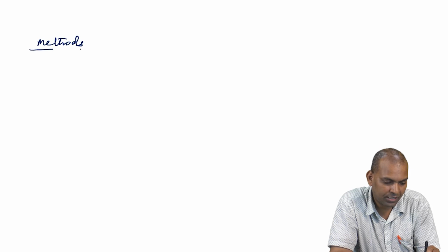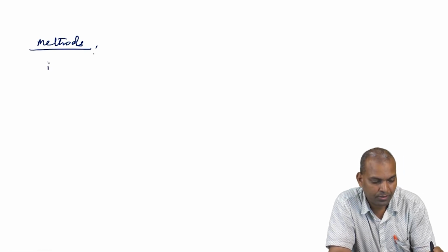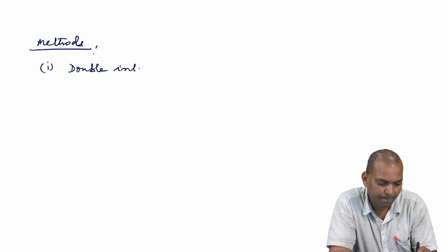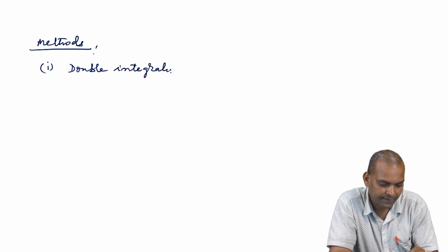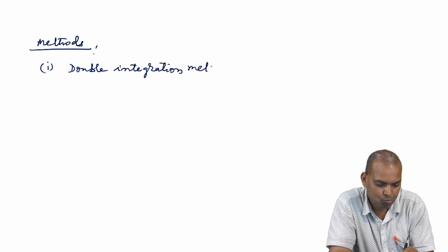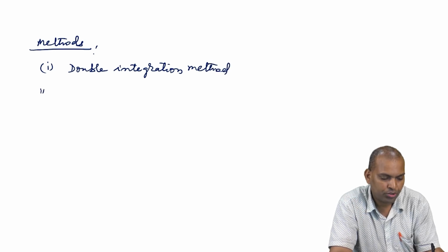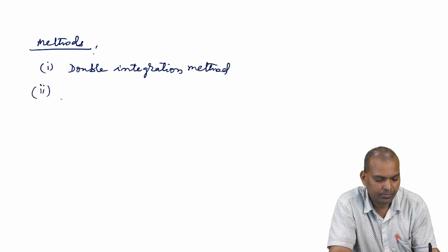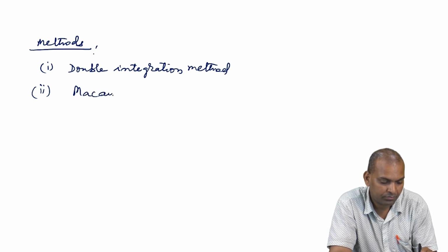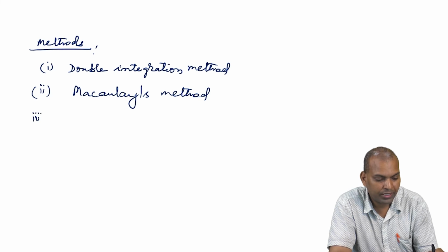To calculate the slopes and deflections, number one is the double integration method. Number two is Macaulay's method. And the third one is the moment area method.